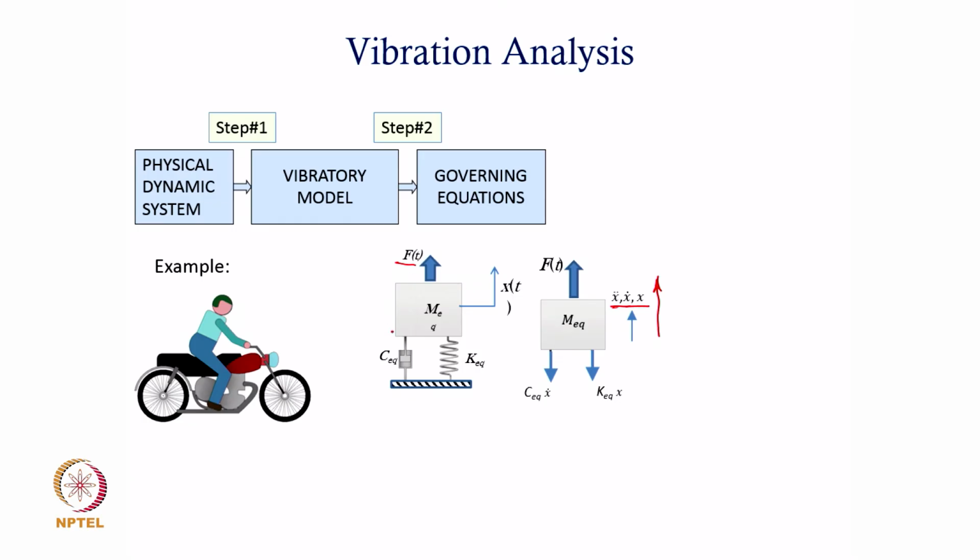So, if I strip this body from its surrounding, what forces do the surroundings act on this isolated body? So, we call this a free body diagram, and all of you have learned this process of getting a free body diagram and identifying all the forces which apply on this free body. Once you identify that, you can apply Newton's second law, and how you apply that is by writing an equation like this.